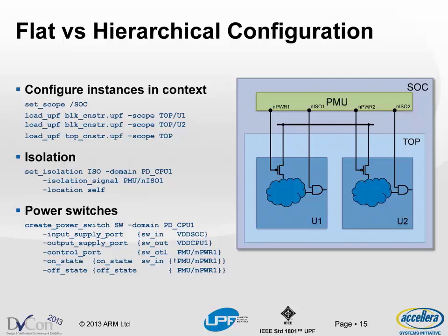However, there are other reasons why you might want to do a bottom-up hierarchical implementation, perhaps due to limitations of your physical implementation tools, capacity management or concurrent engineering. There are a number of reasons why that decision may already be predicated as being a bottom-up implementation flow. So in the case of a Cortex A-series core, it's quite likely you're going to implement the CPU before integrating it into the cluster. So I thought for the rest of this example, I'd go through the hierarchical approach.